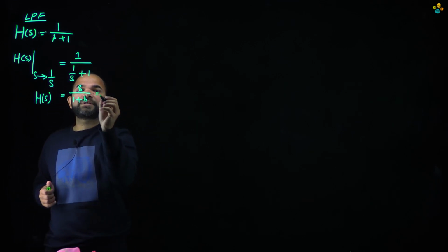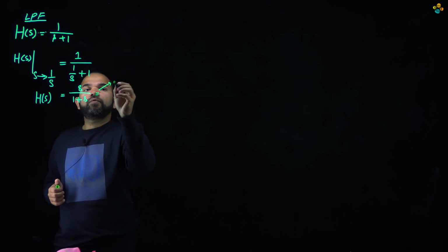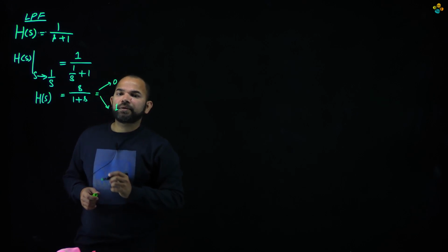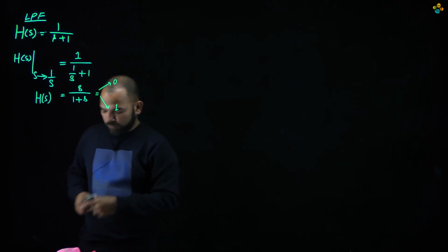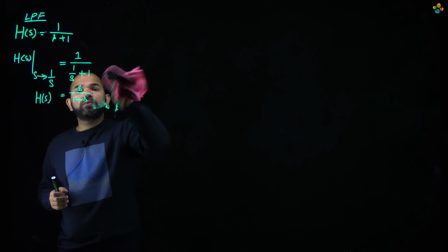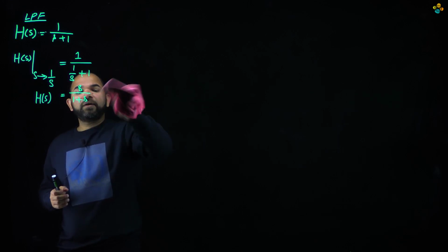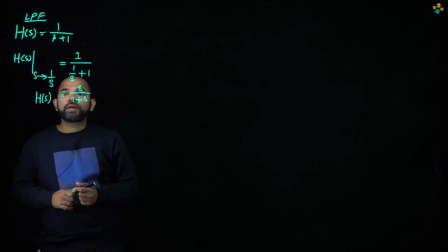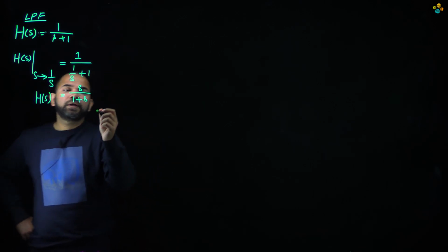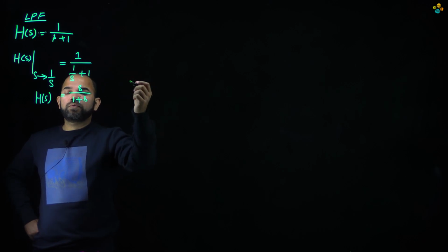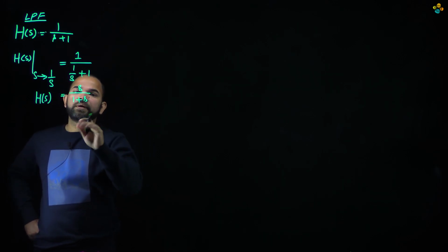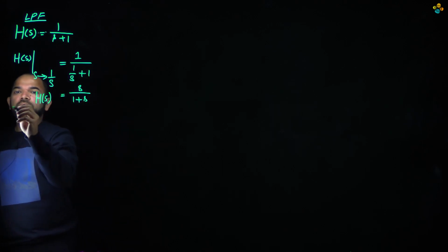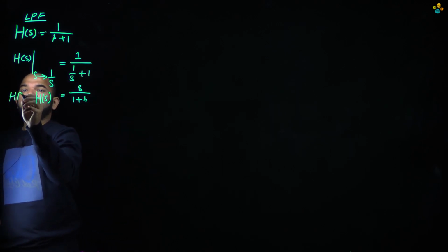So basically for lower frequencies it is 0 and for higher frequencies it is approaching 1. If you are not aware of L'Hospital's rule, please go and visit L'Hospital's rule for calculating limits. Okay, so if this function gives you a 0 transfer function for lower frequencies and 1 for higher frequencies, this is realizing a high pass filter.